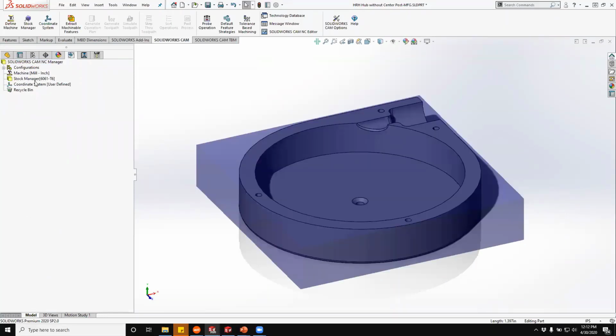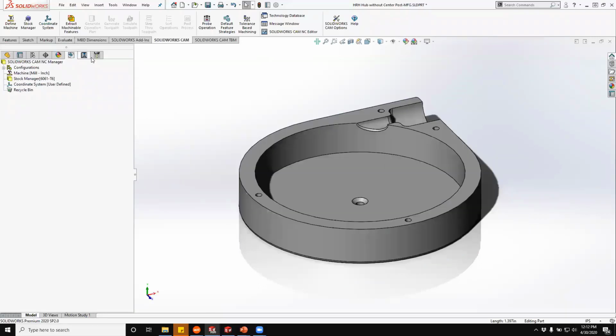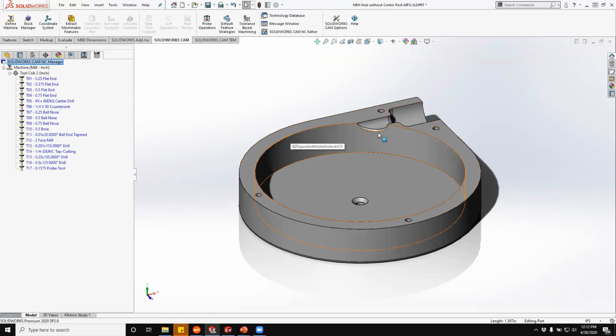And if we were in an old traditional CAM system, we'd probably go over and pick the tool that we want to use, and then we'd start picking the operation that we want to use. We'd start picking some boundaries and things like that. And it's important to note that I can copy that same workflow right here. But we also have a tool called automatic feature recognition. And automatic feature recognition is the power of solid modeling taken into the CAM software, into machining, and that's where the software has the ability to interrogate the part and return back the features that it thinks it needs to make in order to create this part.